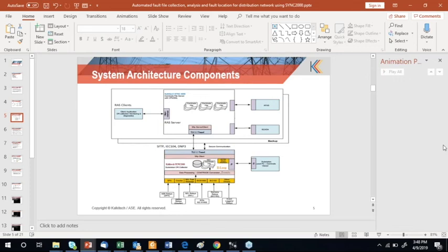And another question is whether you support the Dixie protocol. Okay. So the thing is that there is a difference between the 103 protocol and the Dixie protocol. 103 is basically a general IEC standard, but Dixie is a Siemens customization on IEC 103. So there are additional messages over 103 for the Dixie communication port.